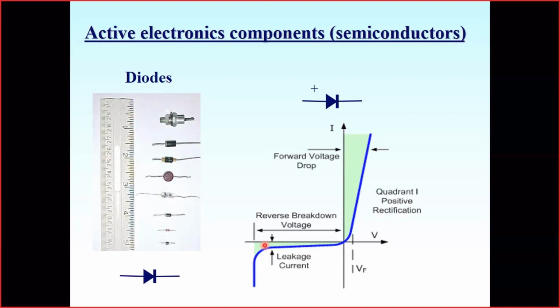And here, it is important how big a reverse voltage we can apply. If we apply too high a voltage, the diode will break through, the breakdown happens, and the diode just burns out. Some diodes are specially designed to operate at the reverse breakdown voltage without any irreversible damage.